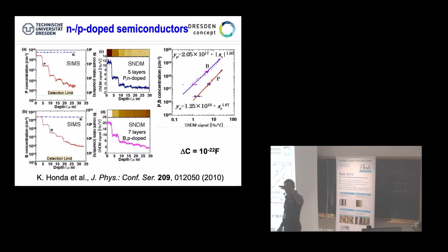In SIMS, you're going to destructively take off part of your surface. You're going to produce steps. The surface here was really produced by growing always 5 micrometer layers of different dopants at different concentrations. And you see here the concentration levels N of what you get. This is about 5 times 10 to the power 18 and down, down, down again. And then comparing what they have in SIMS and SNDM for both the N-doped and the P-doped allows you to really get some kind of calibration curves, these ones. So you can get calibration on the dopant.